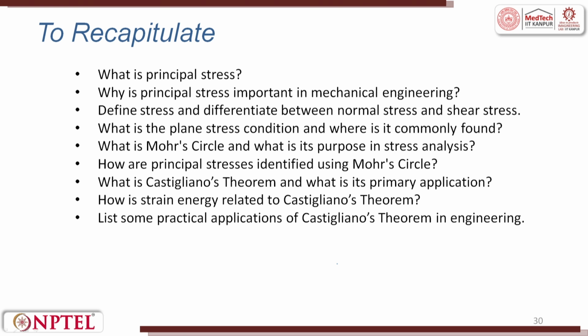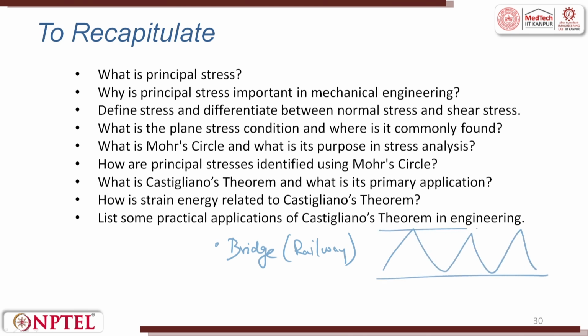Now, what I would request you is to take any bridge structure, right, a railway bridge where a train crosses. So, you will always see a structure like this, right, and what I want is for you to find out how many members are there, what are the stresses they undergo, and if I take an element here or here, try to draw the plane stress condition and assume some value, try to draw a Mohr circle, right.